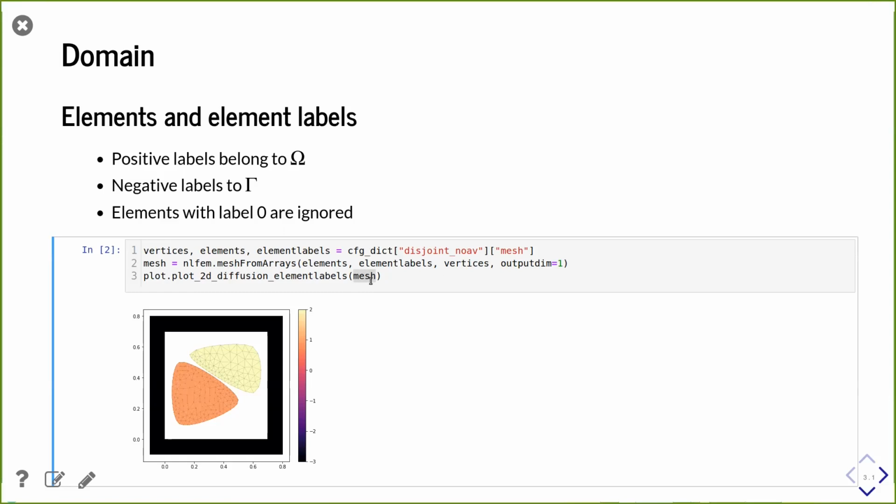So you look at the first line here in that code. There's some kind of mesh produced. I think this is from Gmsh. And this basically needs vertices, elements, and some labels for the elements. Then you see that from that triple, we generate the mesh. The mesh in our case also contains the degrees of freedom information, which would usually be a different thing, but I just dumped everything into this mesh dictionary. So we generate the mesh, and now you see here how this looks.